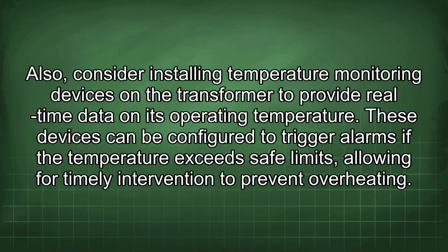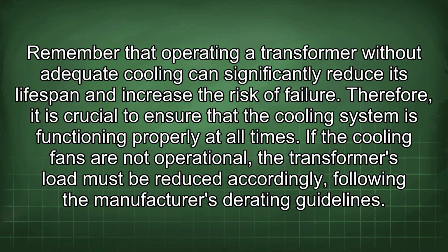Also, consider installing temperature monitoring devices on the transformer to provide real-time data on its operating temperature. These devices can be configured to trigger alarms if the temperature exceeds safe limits, allowing for timely intervention to prevent overheating. Remember that operating a transformer without adequate cooling can significantly reduce its lifespan and increase the risk of failure. Therefore, it is crucial to ensure that the cooling system is functioning properly at all times. If the cooling fans are not operational, the transformer's load must be reduced accordingly, following the manufacturer's rating guidelines.